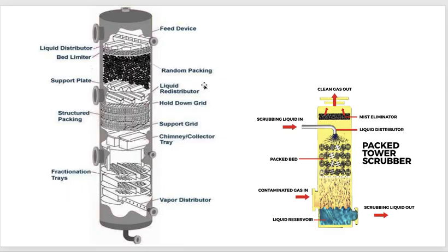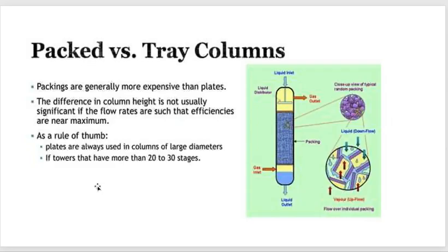Here in this tower, you can see easily there is a packing section above and a tray section down. For sure we can find a mix of both of them in the same tower. Some cases will prefer a tray tower, and other cases will prefer a packed tower. We will know in detail which cases support choosing the packing and which cases support selecting the tray tower.